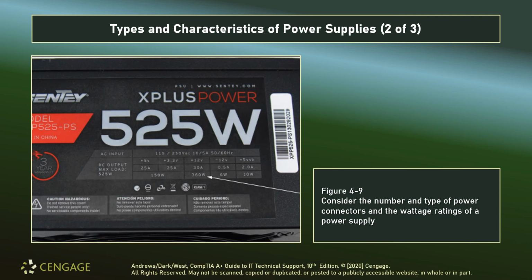So we would need to look at each particular component that we have in our list and say, okay, is this going to require a 12-volt connector? Is this going to need a negative 12? Is this going to need a plus or minus 5, 3.3? I don't really require you guys to worry about the minus 12 or 5 VSB because they're not predominant connectors for a lot of components. They're usually internal only, maybe for the CPU, auxiliary power connector, and what have you. The 5, the 3.3, and the plus 12 tend to be the ones you look at more so for your additional components, for your drives, for your graphics cards, etc.